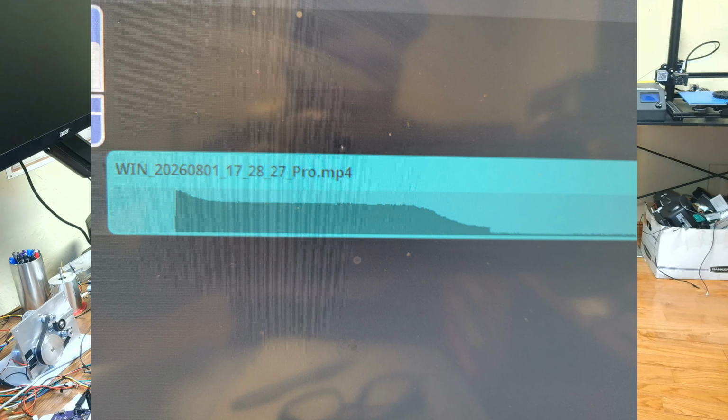So you see that the tone of the buzzer did change as we divided the frequency to slower. I can't get it on the scope because it starts out high frequency and then it changes too many divisions for the scope to show it all in one. But here is a graphic representation of it right here, and you see it's not linear, and it's probably because it's a buzzer and not a speaker. But we're dividing by 2, but anyway, that's how you can use the PWM to control a buzzer or other things. That's how we control the buzzer and make the sound and the length and the duty cycle, so you can use less power.